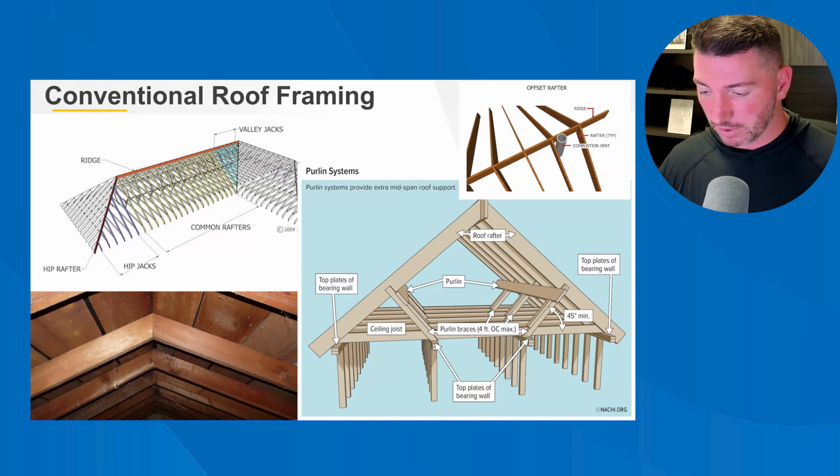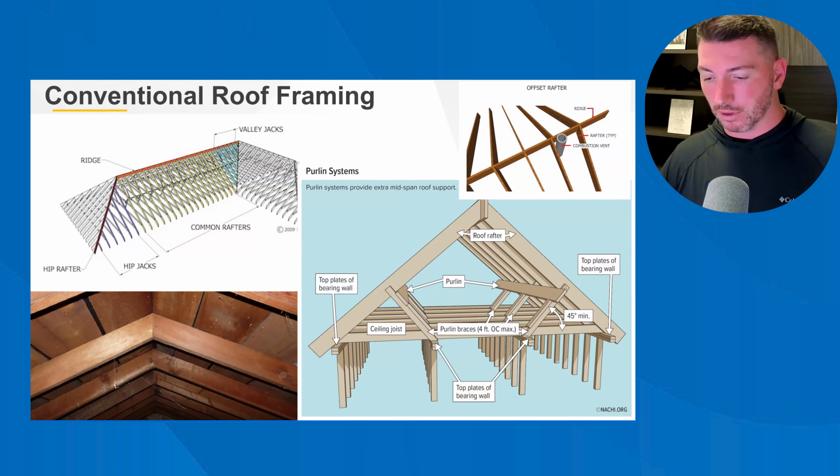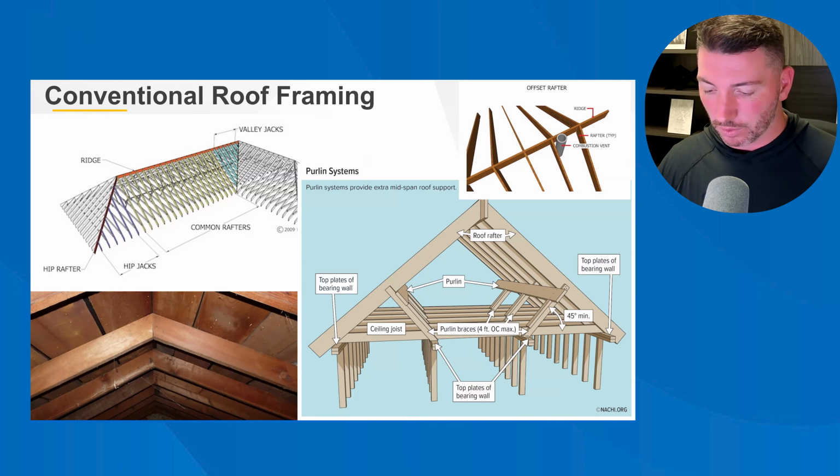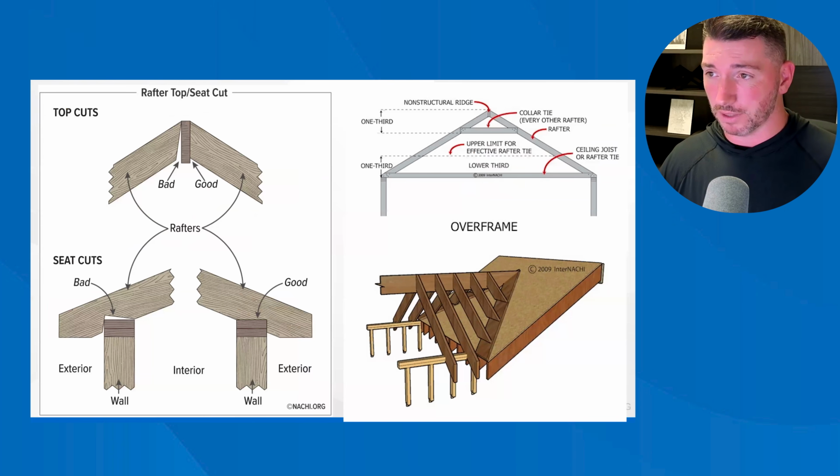In newer homes, many rafters which don't oppose may indicate poor quality framing. It's an indication that you should look carefully for other problems. And that's pretty much true for every little workmanship issue you see. I would definitely be on the lookout for other issues when you see bad workmanship.